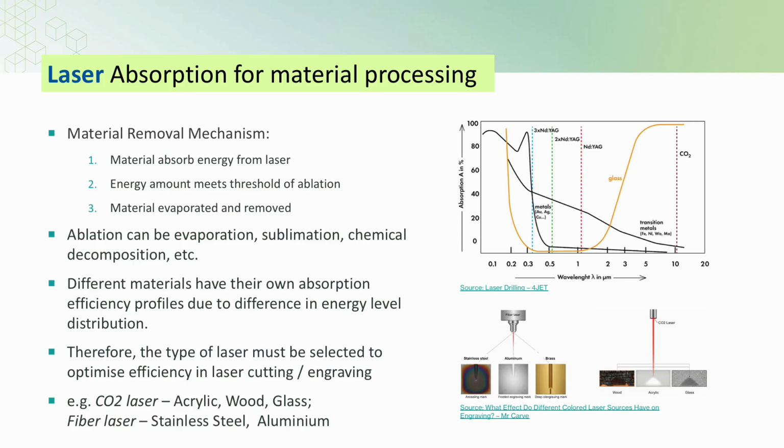Secondly, the amount of absorbed energy meets the threshold of ablation. Ablation can be evaporation, sublimation, or chemical decomposition. Finally, the material is evaporated and removed. As mentioned previously, different materials absorb different wavelengths of energy. Suitable lasers must be selected to optimize the processing efficiency.